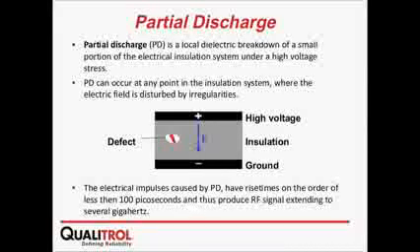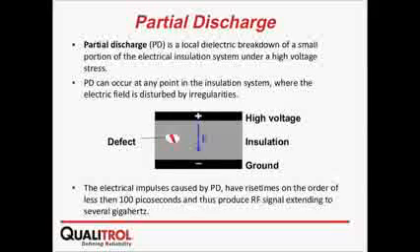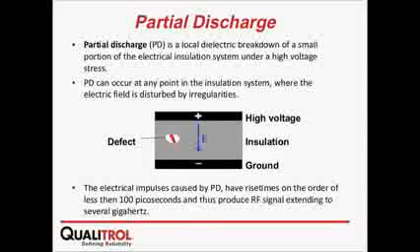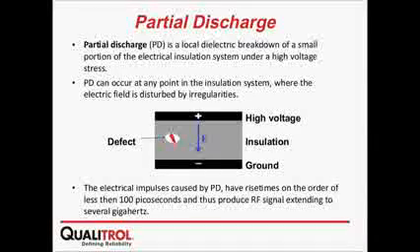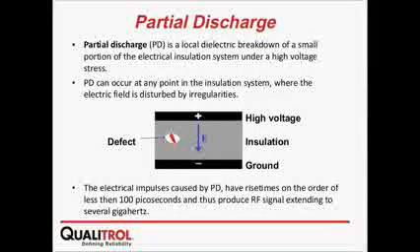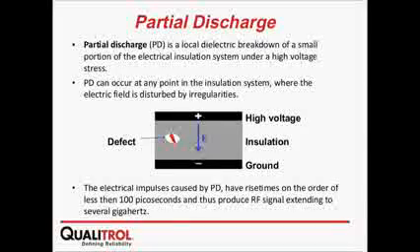So at some point of the insulation, if you have irregularities or an increase of this partial discharge with the high voltage stress, this insulation will become a conductor. When it becomes a conductor, it allows electrons to flow through it. If it flows from plus to minus, as shown in the picture, then it would be the flashover.